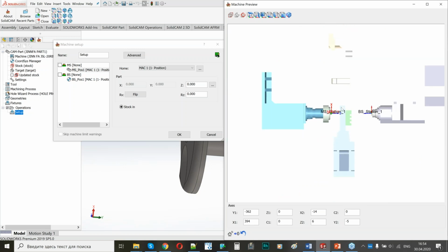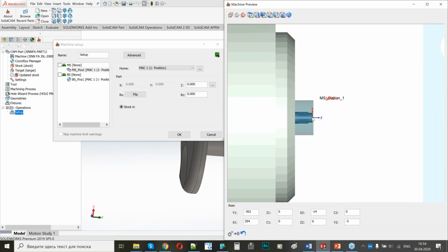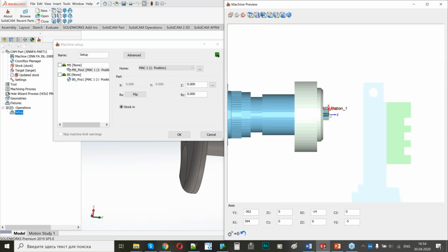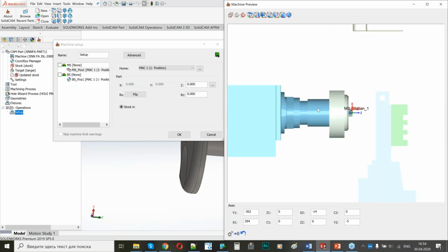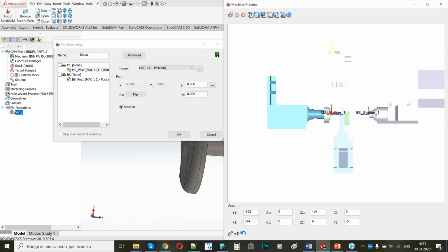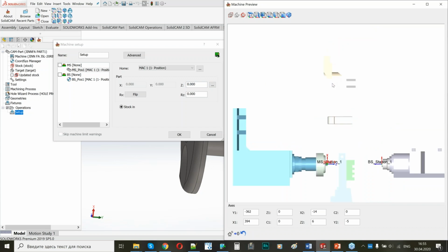Okay, so all the programming for the Swiss type starts from the 0 point. So this is 0 for the machine, and I need to move this clamping device to give the bar some distance. So this device could move towards the guide bush. So here I should enter the number which is called machine length, and this number consists of the length of the part, the length of the tool holder, of the cut-off tool, thickness of the holder of cut-off tool, if it will be rotated, if it will have the right direction insert.